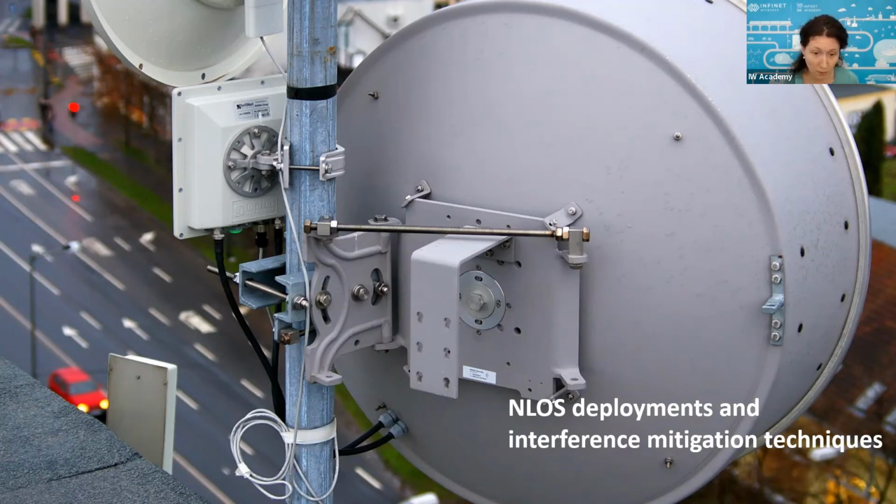Is there a problem if we put maximum power on short distance? First of all, you should check if you are allowed to use that maximum power in your country. And then you should see if there is other equipment or radio systems, for example, working in the area, because you might interfere with them. If your country's regulation allows the maximum power that you want, you can use it, but you must take into account that you will increase interference in the area. So you might have complaints from other systems.